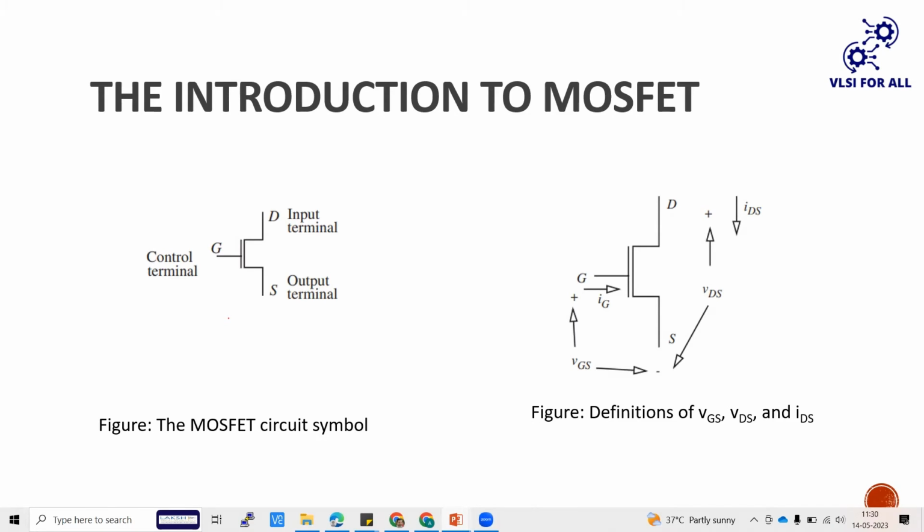Then here you have not shown anything, simply you have drawn one MOSFET. Yes, we are from digital. There are different symbols for analog MOSFETs and digital MOSFETs. Here we are considering digital MOSFETs where we don't give any arrow marks. Instead, for P MOSFET, we give one circle at the gate terminal. For N MOSFET, we don't give any circle at the gate.